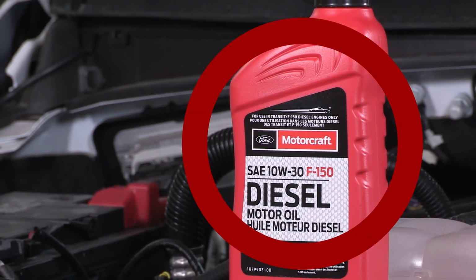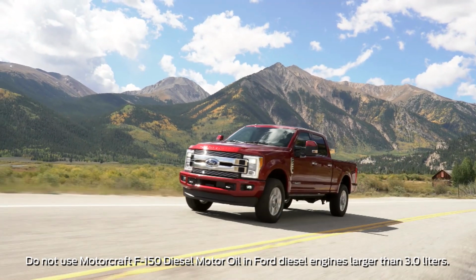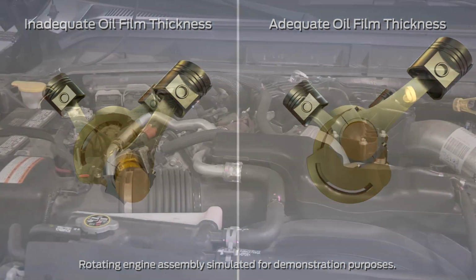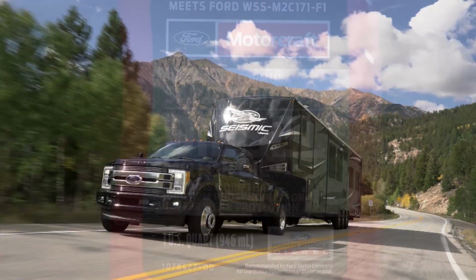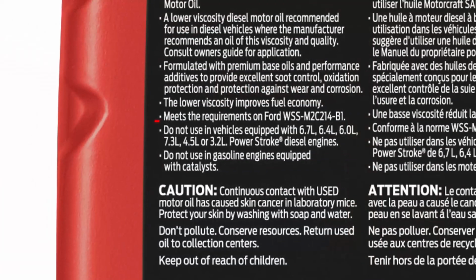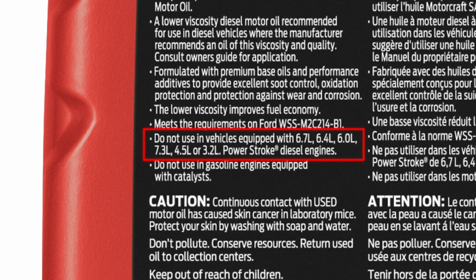Do not use a Motorcraft F-150 diesel motor oil in Ford diesel engines larger than 3 liters. It will not provide adequate oil film thickness to protect the components in larger Ford diesel engines. These larger engines require an oil meeting WSS-M2C171-F1 spec. You can find a list of engines to avoid listed on the F-150 diesel motor oil bottle.